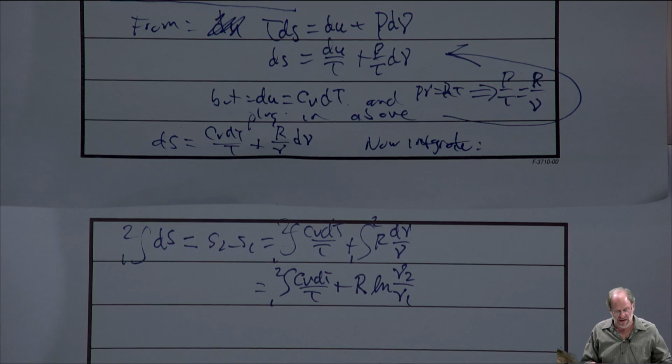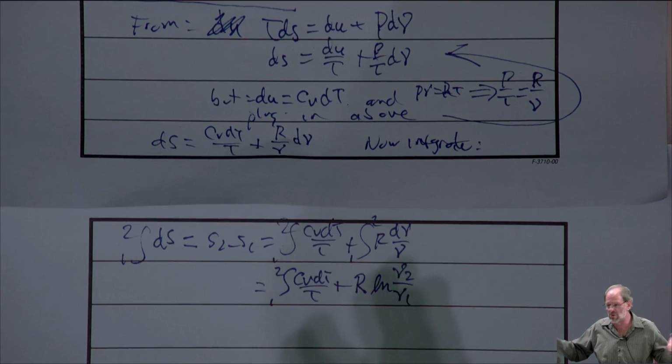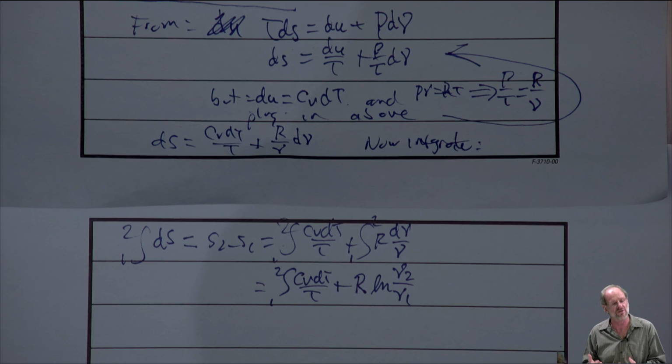But again, we have to think back to when we were talking about this material in solution to the first law problems. I do have a table for ideal gases that gives me a functional relationship between specific heat and temperature, right? It's from table A2 part C. But I've also said that I'm never going to ask you to actually do that. I don't want you to have to take the CP bar data from A2 part C and then convert that to CV data and then go through an integral of a third order polynomial equation. It's not that you couldn't do it, but it would be perfectly acceptable to me if we just estimate CV as if it were a constant.